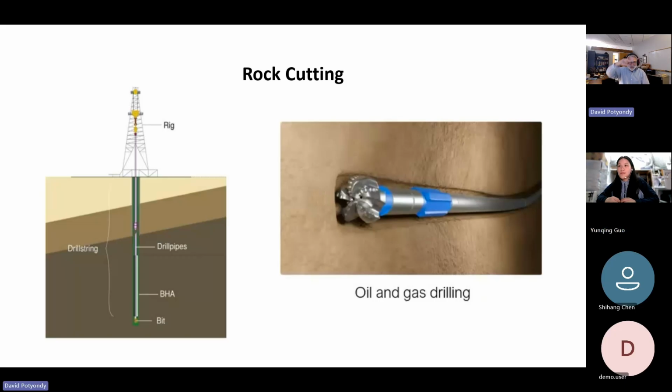So you could load it, but now you might have 4 MPa confinement when you load it. And it will take higher load before it starts to fail if you confine it. Because for the rock to break, when it starts to break, it has to expand. And if you prevent the expansion, it's stronger.